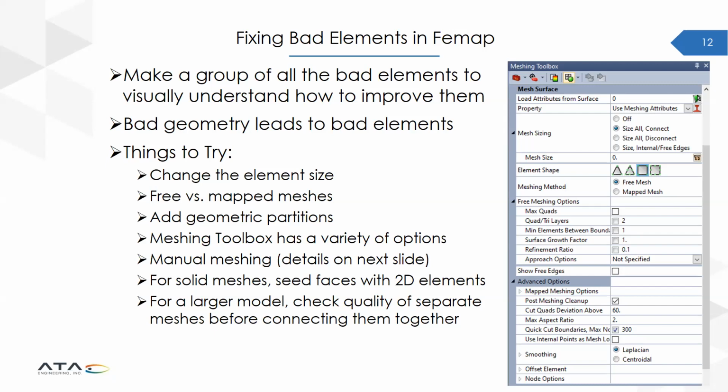And related to mapped meshing, if you can, it's good to divide your part into geometric partitions to help maximize how much of it you can mapped mesh, like dividing the face or splitting the body when appropriate.